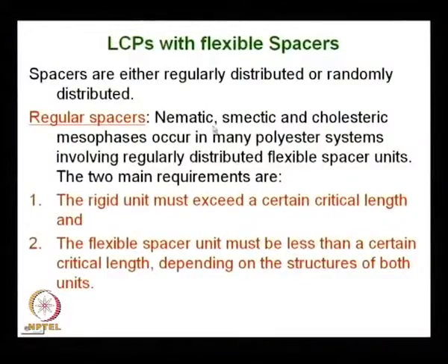Regular spacers: nematic, smectic and cholesteric mesophases occur in many polyester systems involving regularly distributed flexible spacer units. The two main requirements are: the rigid unit must exceed a certain critical length, and the flexible spacer unit must be less than a certain critical length depending on the structures of both units. These are all self explanatory. If you devote your time, I think your concept will be clear.